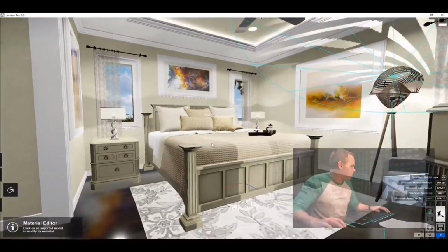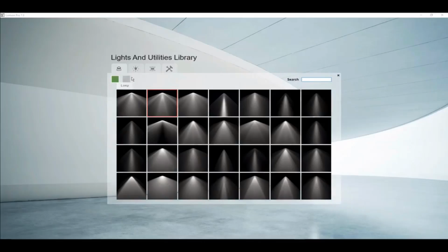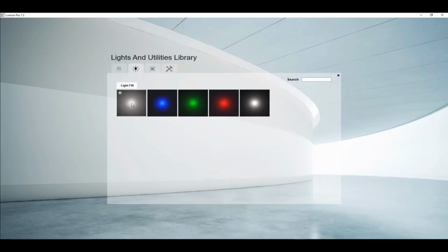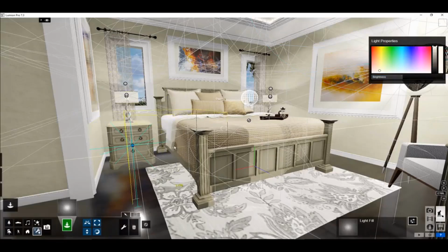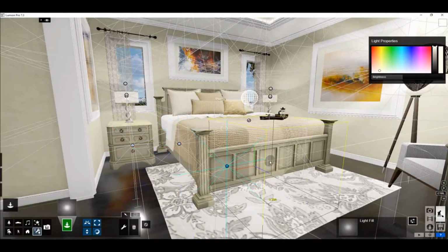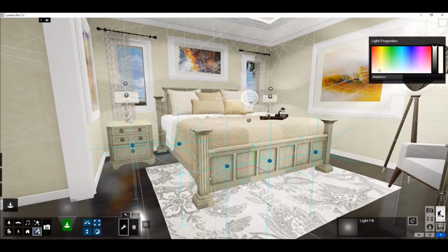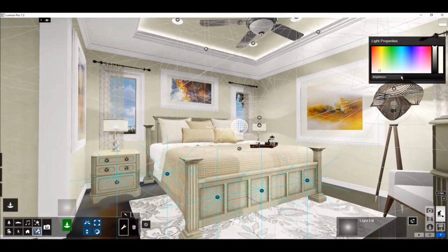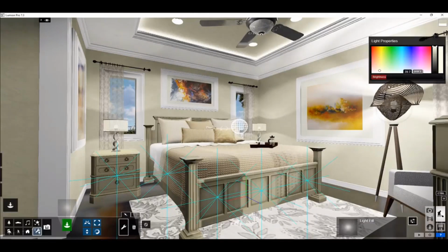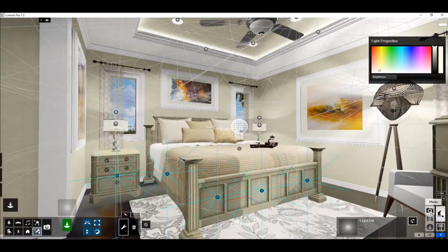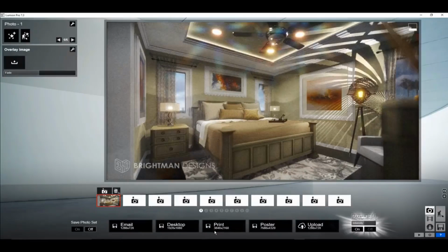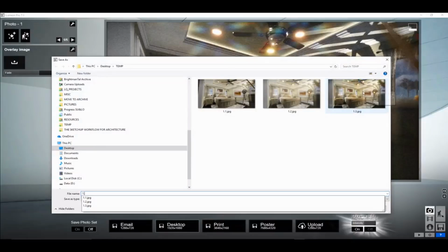I'll just go into build mode and choose objects, select objects, Omni-Light, and here's my light fill. All right, so I can just kind of click on a few of these different places here and add those light fills. And I'm going to select my light fills. I'm going to hit deselect all and then select all similar. So I've grabbed all those light fills, and see those are at 1500. I think maybe 500 is about right for that light fill. All right, and we're going to render this one as image 1.4. So let's render this one more time and call this 1.4.